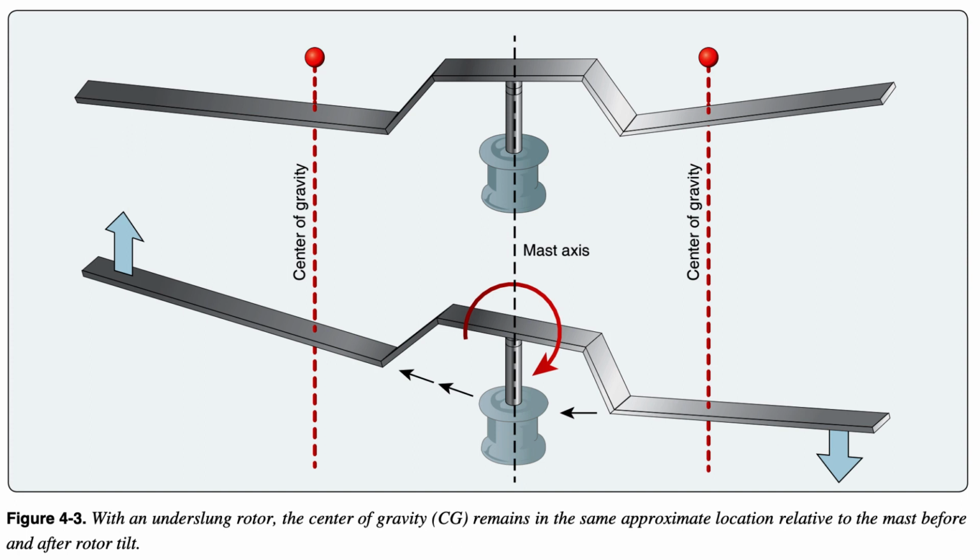It is the violent contact between the static stop and the mast during flight that causes mast damage or separation. This contact must be avoided at all costs. Mast bumping is directly related to how much the blade system flaps. In straight and level flight, blade flapping is minimal, perhaps 2 degrees under usual flight conditions.